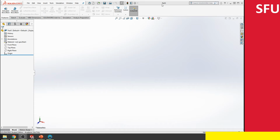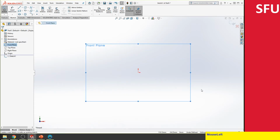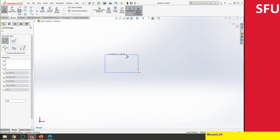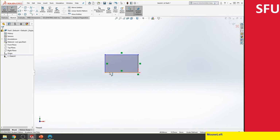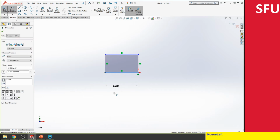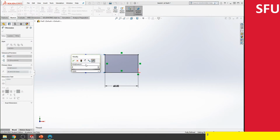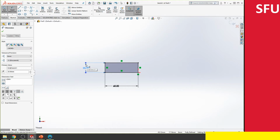And we would create this particular part. So maybe let's create this at the front plane over here. So for that, we're going to create a rectangle. And like so. And then we give some dimensions to it. So we'll call this maybe 60. And then we'll call this 20. And then click enter, and then we have the particular shape that we have.